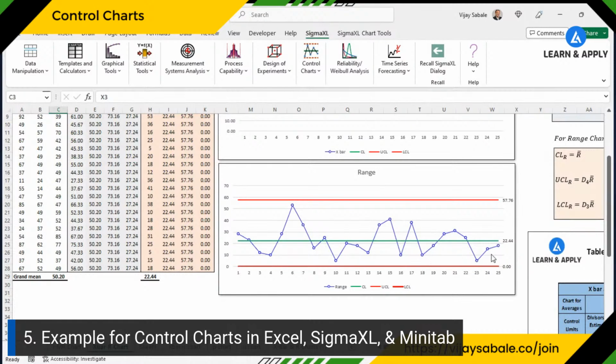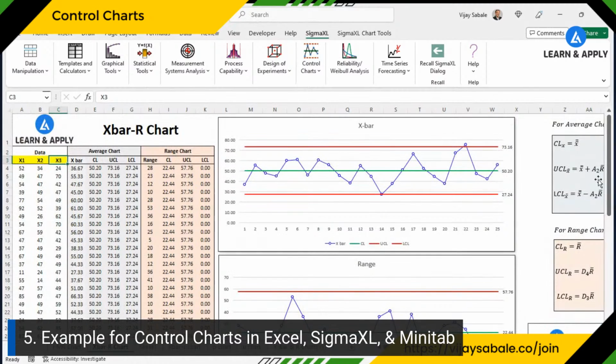By looking at the range, we can see all the points are in control. So we can look at the X bar control chart. And again, that is indicating the point number 22, which is the presence of special cause. Now, as this is a template, it is not indicating to you that there is a presence of special cause and that we should take action. So we need to understand that. That's the thing in case of this control chart template.